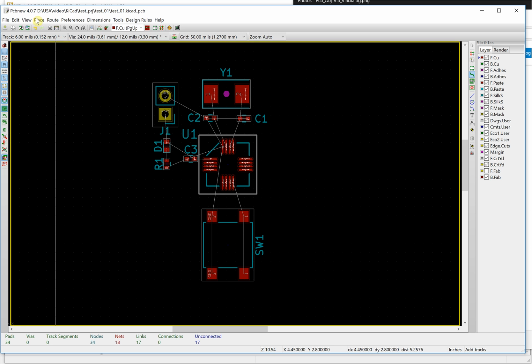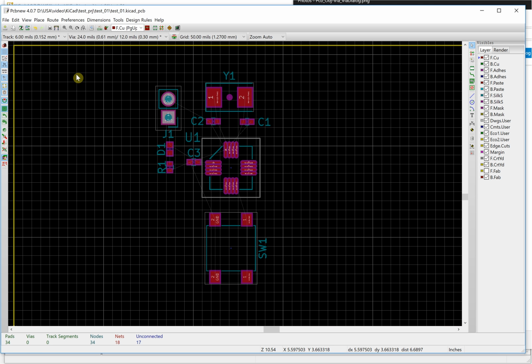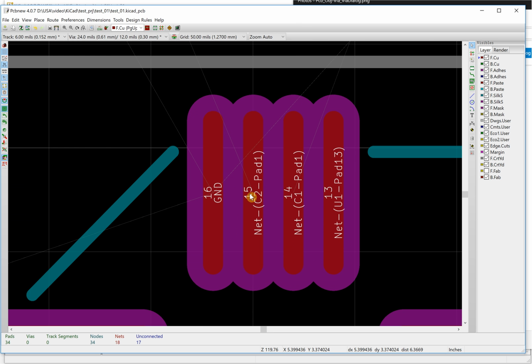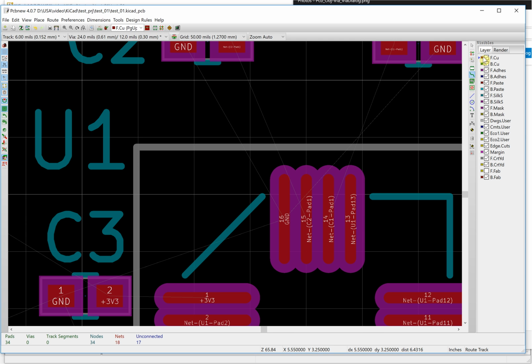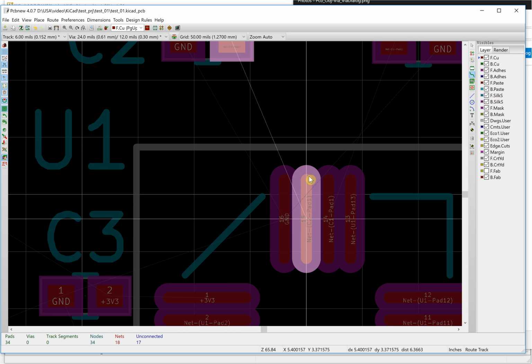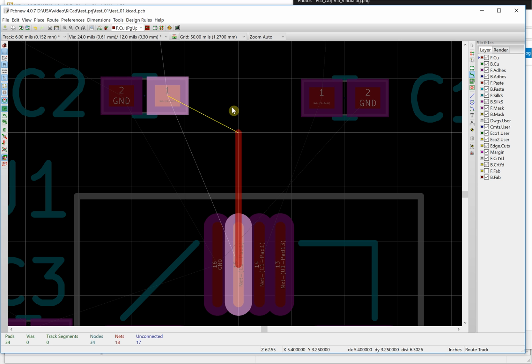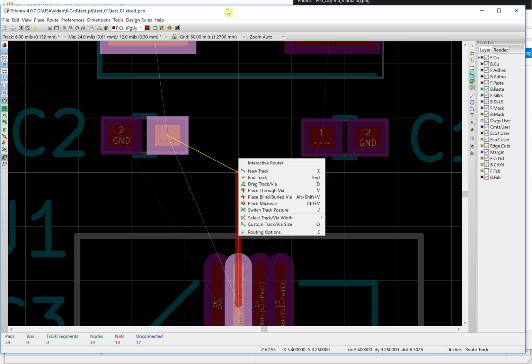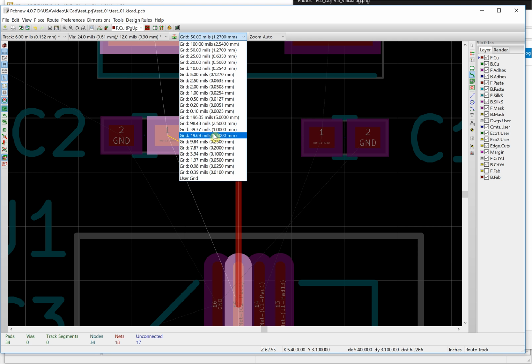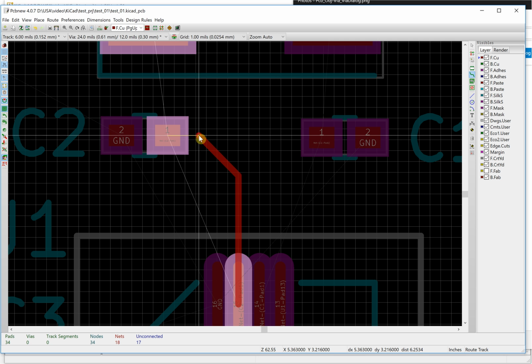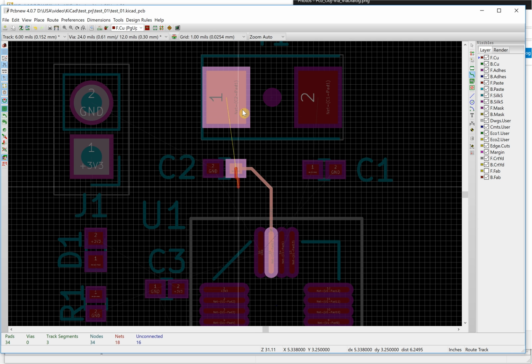When you do this, you'd better change the view to OpenGL. The OpenGL view will make the display more smooth, so it's better for your drawing. Okay, so select this and keep this. This is front layer, and we click here. You will see the size of the grid is much bigger, and then the trace will run on the grid. So we can change the grid size much smaller, and then we can more easily trace it. Okay, so we change it to 1 mil. So you can see it's more smooth. Okay, click, and then we click.